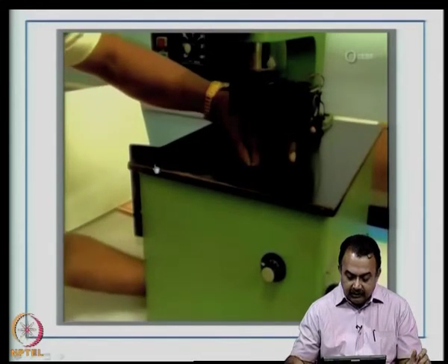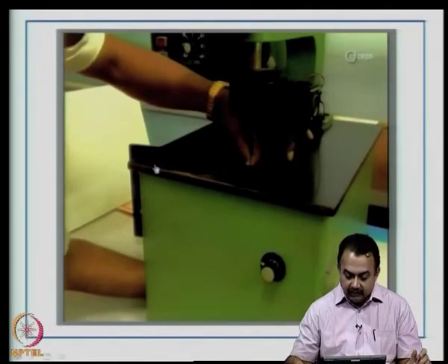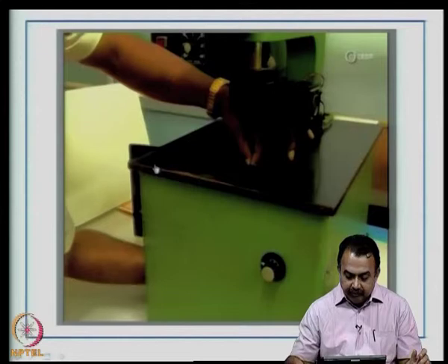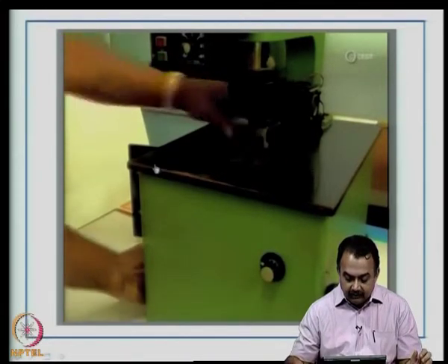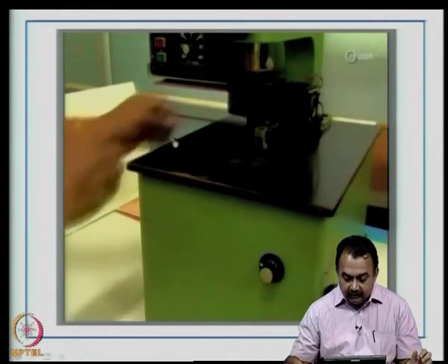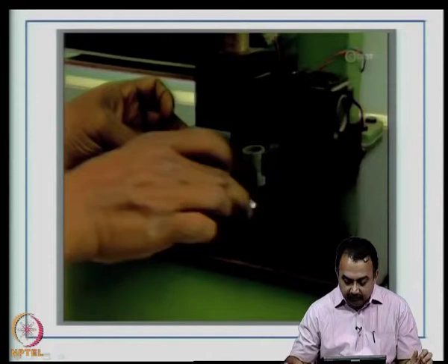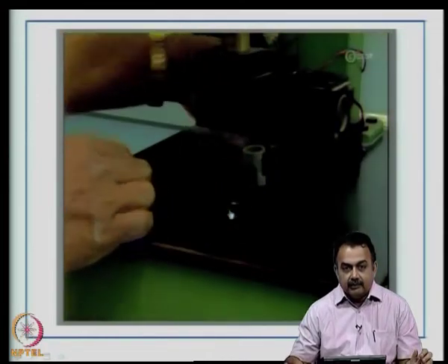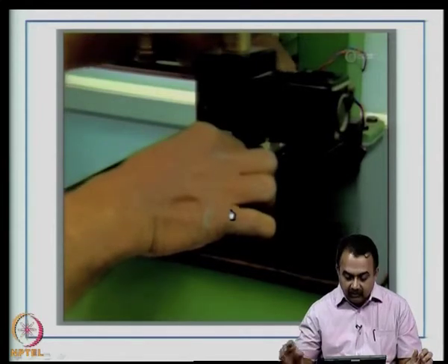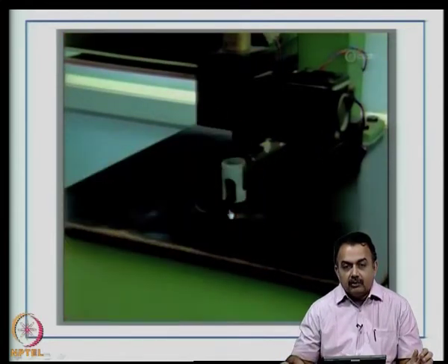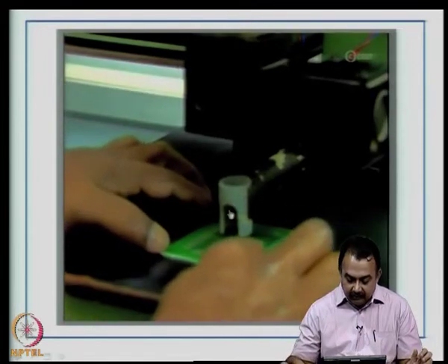So, sufficient height is given during the fixing of the drill bit. Here again we are using tungsten carbide, and as you can see here the drill bit is protruding. This height is very important because that defines the PCB board thickness for a complete through and through drilling. It can't be a through hole that is only partially drilled through the depth of the laminate.